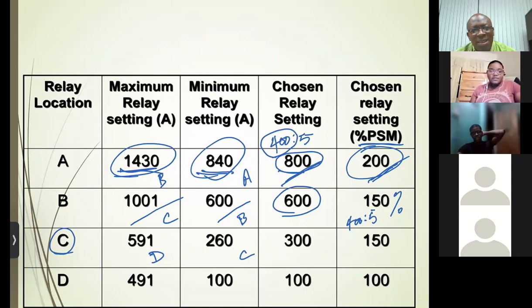No, sir. I get what you're saying, sir. The relay only has one set value, so the multiplier adjusts it. So it has the 400. So if we wanted to go to the 800, we have to choose the 200% multiplier. Just double it. Yeah.